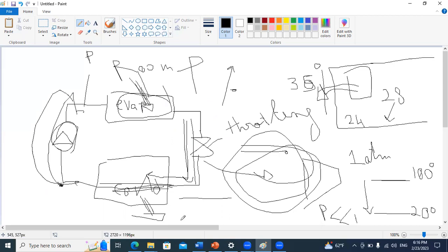Now, in case I need to produce a heating effect, my room should be on the condenser side, and then the evaporator will be on the outer side. By just putting work, here I am putting electrical work to operate my pump, I force heat to go in a non-conventional way. It will go from low temperature to high temperature, while if I leave it to nature, it will always go from high to lower temperature.